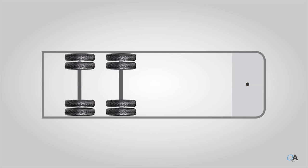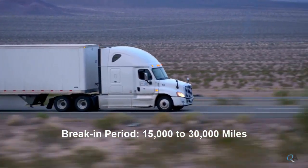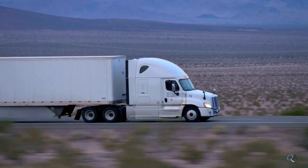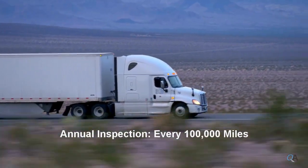The last key point of RP 642 is the recommendation for alignment as a preventative maintenance measure. A total vehicle alignment is recommended after a break-in period of 15 to 30,000 miles. The break-in period is when the vehicle experiences the majority of its dimensional changes from its original manufactured condition. RP 642 also recommends subsequent alignment checks every 100,000 miles.